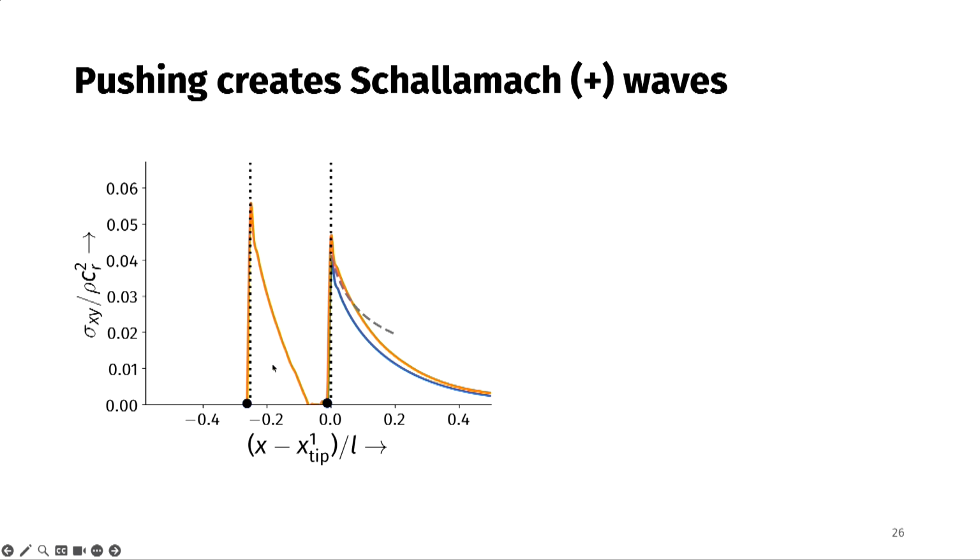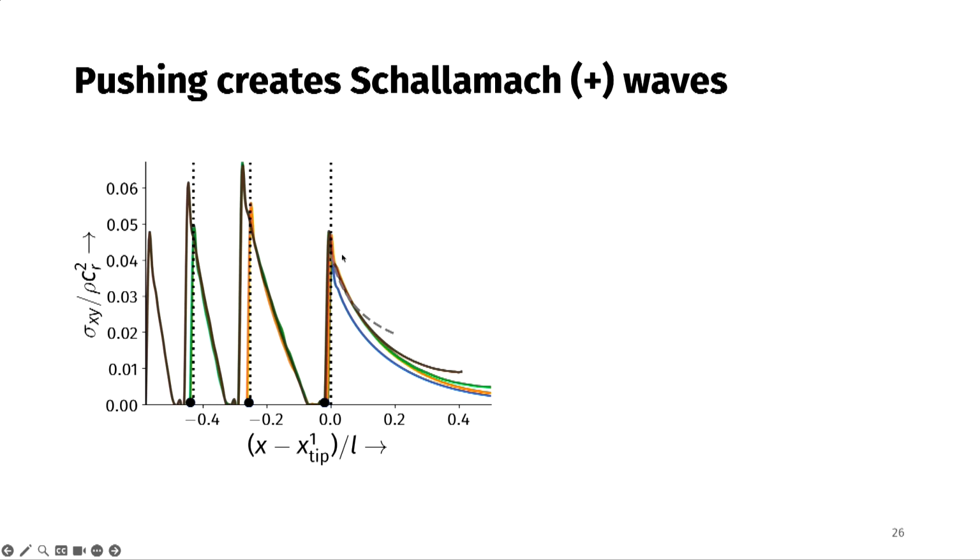This is at a later time after the second pulse is formed. So the second pulse forms behind the first. The origin of this is again at 0, which is the first pulse location. This coordinate is co-moving with the pulse, right? And so the stress state ahead of the pulse doesn't change. Now at another subsequent time, it remains the same, even though other pulses are nucleated behind. So this 1 by root r type of thing appears to be robust as the wave keeps propagating.